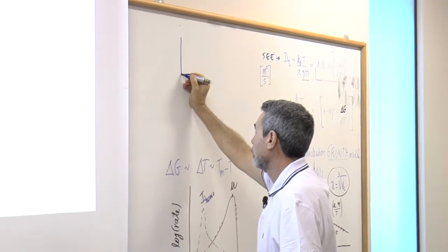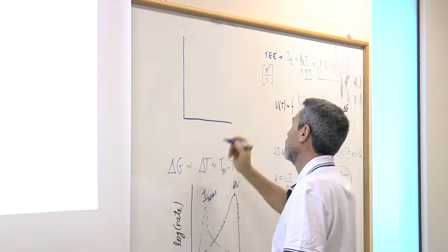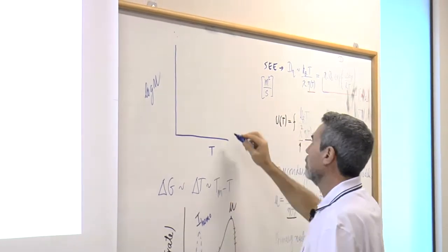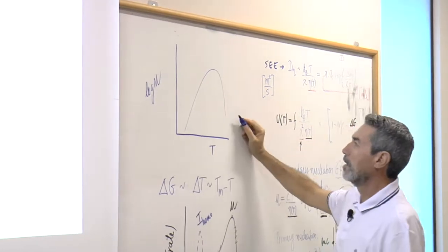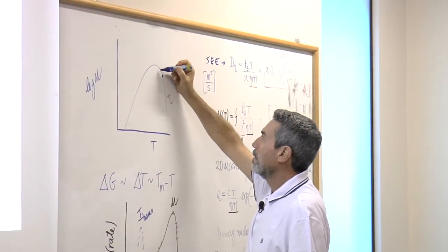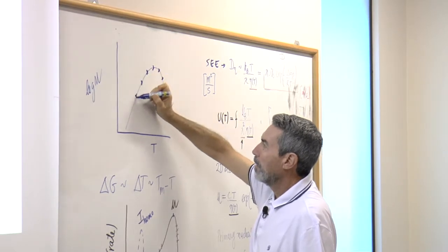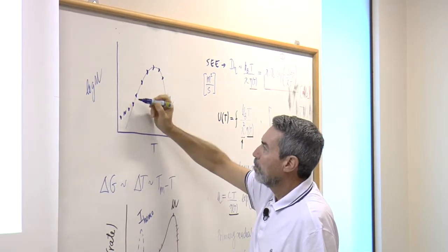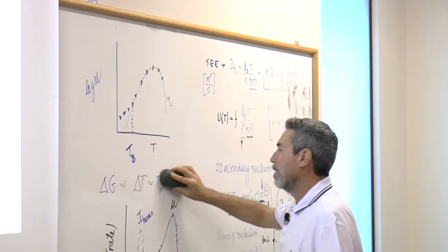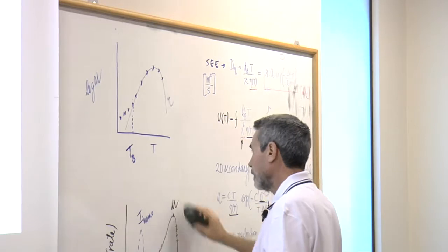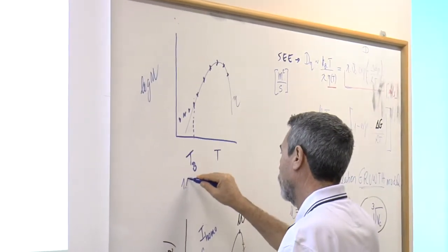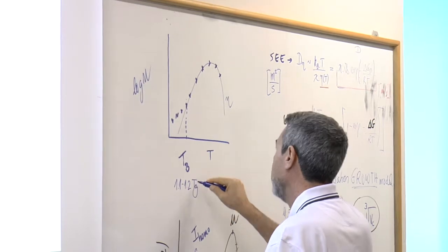If you plot the log of growth rates versus temperature, there is a curve calculated with viscosity, and the growth rates are okay, and then normally there is a breakdown at T breakdown, and this temperature of breakdown is around 1.1 to 1.2 above the Tg of the glass.